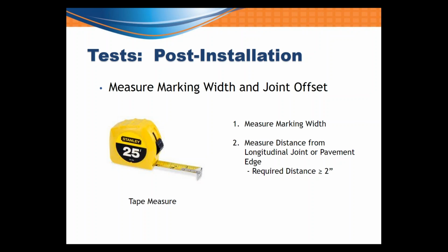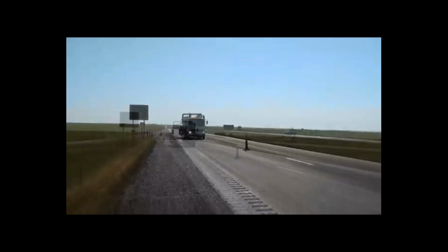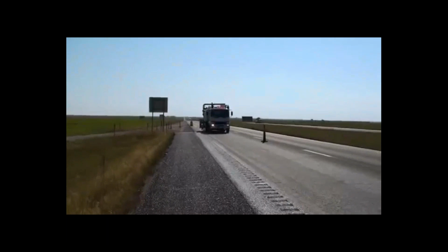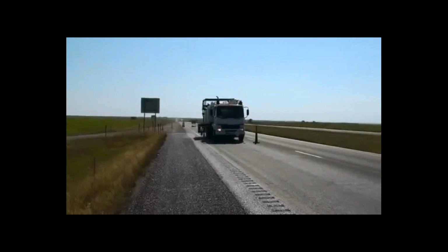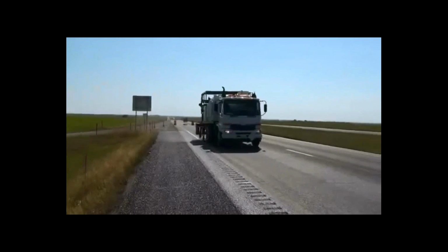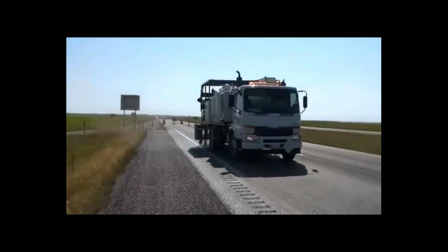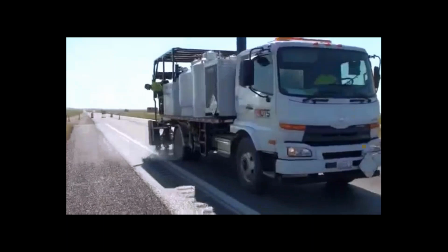Finally, I'm going to show a video that demonstrates proper pavement marking using a truck. And here you go. As you can see, it's going to be a 3-gun system. The first gun is shooting the liquid marking, followed by the next 2 guns placing the beads. This is also referred to as a double drop of beads.